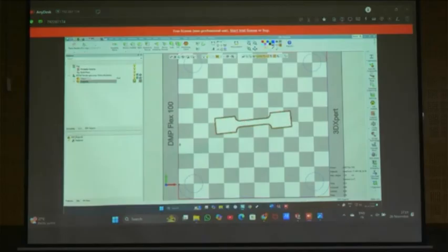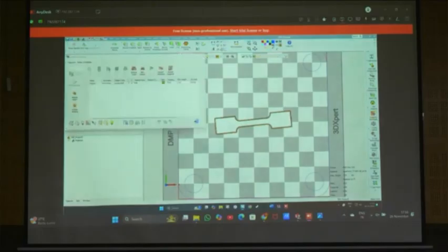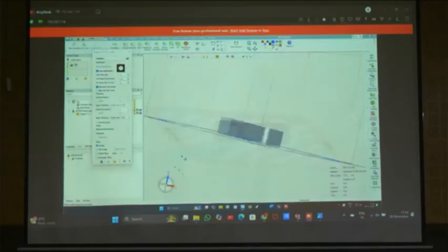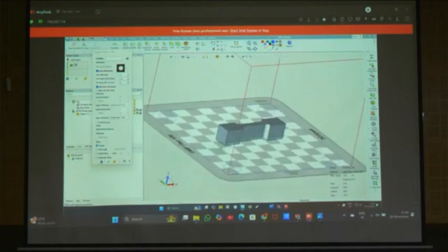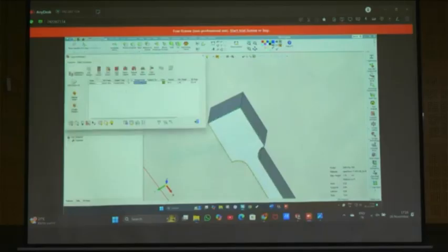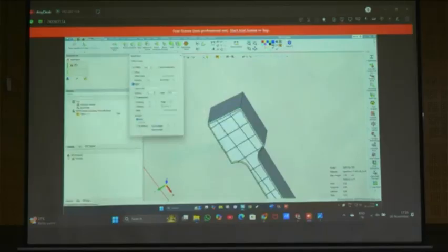But I will show one more thing: I applied the solid lattice, right? I will show how we can apply wall type supports. I will delete this. Delete support, not region. So, wall support. See. But the problem here is internally it is not applying. Wall means outer body only, right? So we need to do something else. Add pattern, so that it will add the pattern, like this.